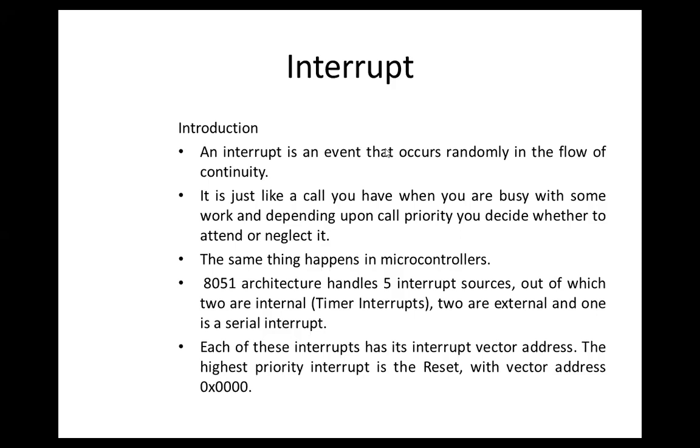You have to search this and see how to get the square wave, or how to see the square wave using the Keil software. There is a CRO in your laboratory. You can use the CRO, or you can use the DSO, where you have to see the square wave. Here we have to connect the ports.